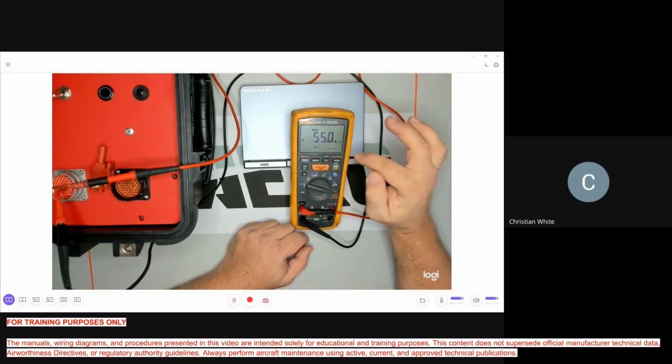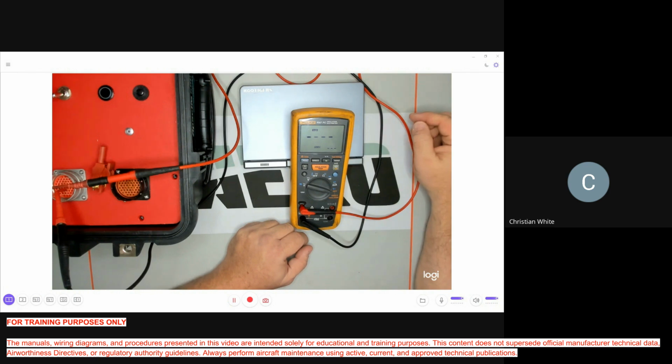Now I know I have nothing there. I'm going to bump it up, whatever it is. If I'm going through anything with a winding, such as a pump, whatever it is, if I'm just doing wiring, I can still jump up to 500, give it a test. The max value I'm going to see at 500 is 550 megaohms. I see that. That's basically showing me it's a perfect test. Give it about 10 seconds. It's not changing. I'm going to stop the test.